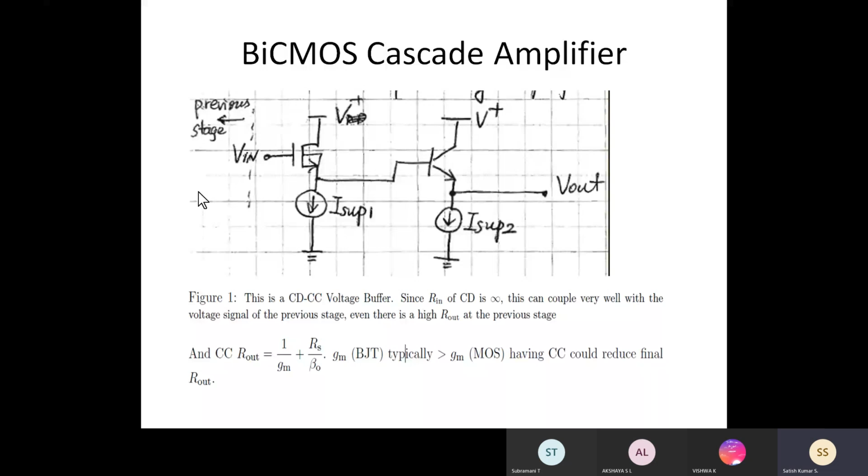Anyhow, from the title you will come to know we are going to combine two amplifiers. One is a bipolar BJT, another one is a FET amplifier. Okay, here they have given a simple way to understand your common drain amplifier. In the FET, drain is taken as the common terminal. So the first stage is a common drain amplifier. For the second stage we take a BJT. The BJT is a common collector amplifier. So here a common drain and a common collector are cascaded.